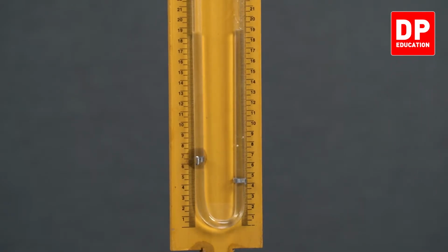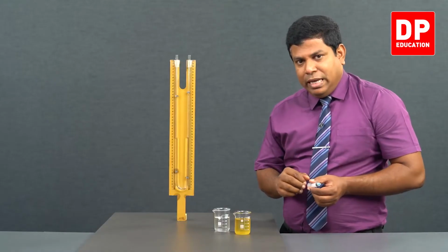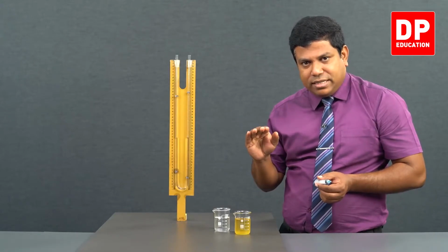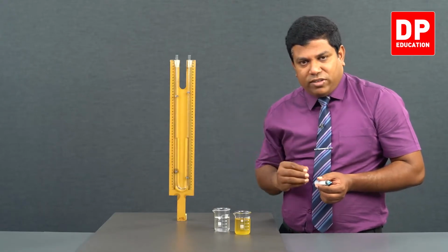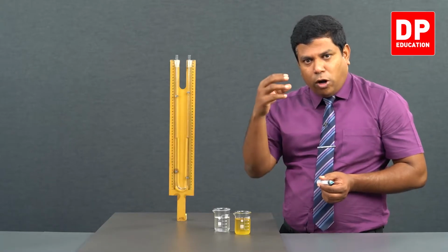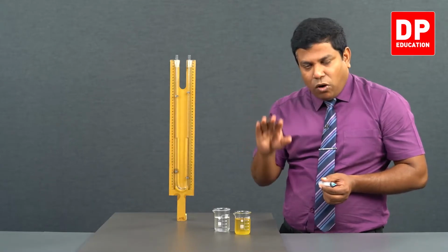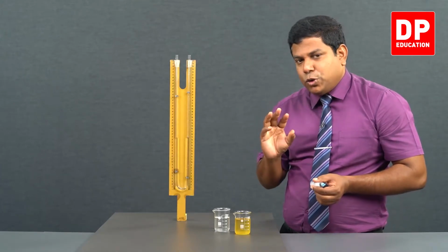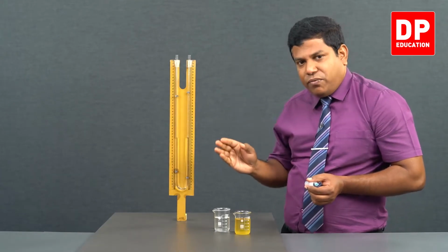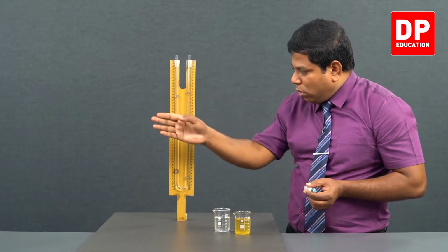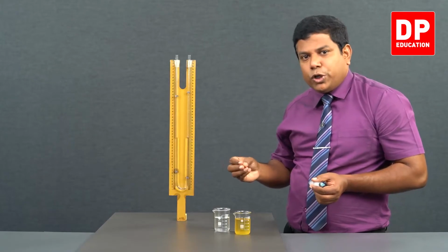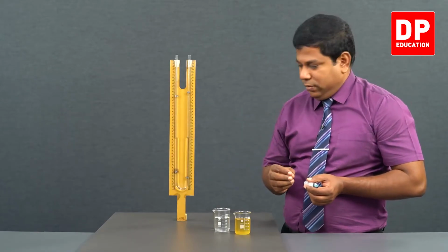After filling it with water to the desired level, give it some time until the levels become balanced, and sometimes on the internal wall of this tube, there might be some water drops stuck on it. So let it fall down and it comes to a stabilized level. After that, to one arm of this U tube, either on that side or this side, I am going to fill with oil.